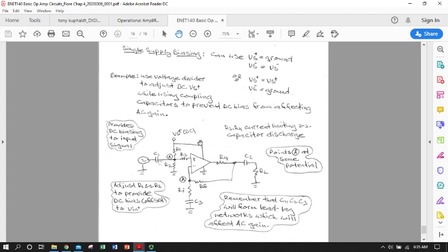So some op amps are designed to be supplied from one side, so you can hook the appropriate terminal to ground instead of having to have a split supply. Of course, if you need a split supply, we all know how to use a voltage divider to get one.